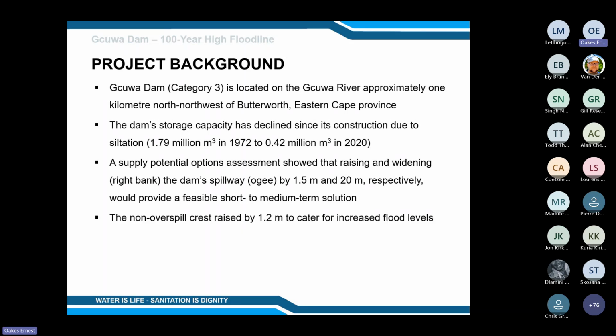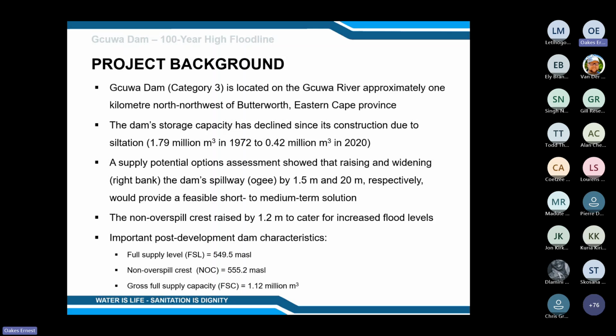And just important to note that the non-overspill crest is also planned to be raised by 1.2 meters to account for those additional floods and the increased flood water levels, as a result of the changes in the dam.